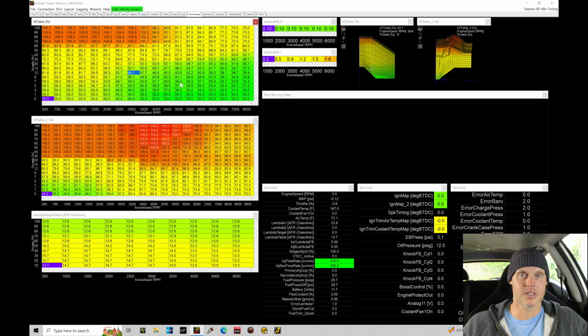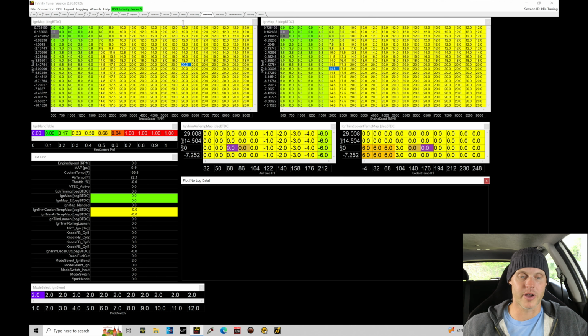Now we chose, in this case, to go about our spark timing using our MAP pressure sensor. If we flip over here, this has our traditional MAP pressure input to our table. We can always switch this to throttle position if we find that this is not consistent enough. However, spark timing has less of an impact in terms of what we're commanding at various vacuum movements in our MAP pressure range compared to our fueling with our throttle position. So that's why I have a hybrid alpha-N style strategy going on here.